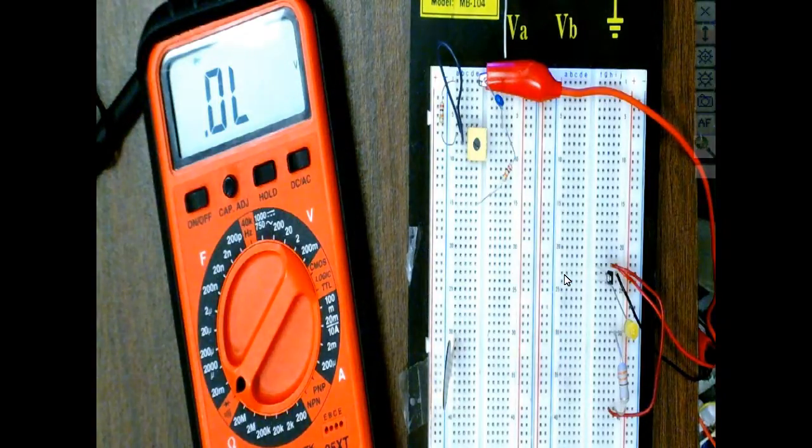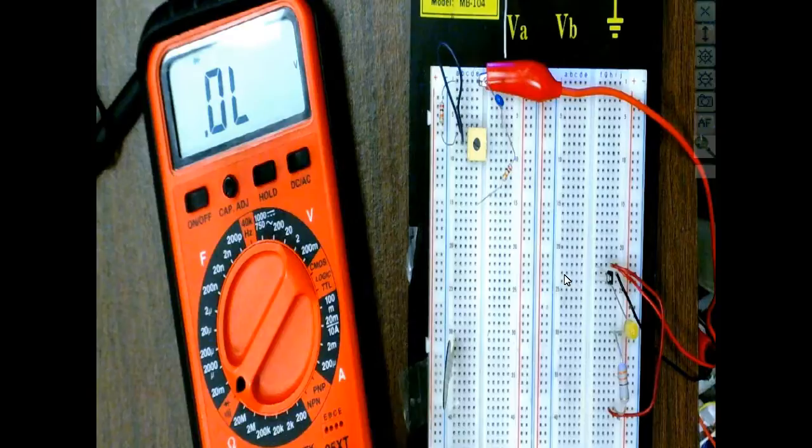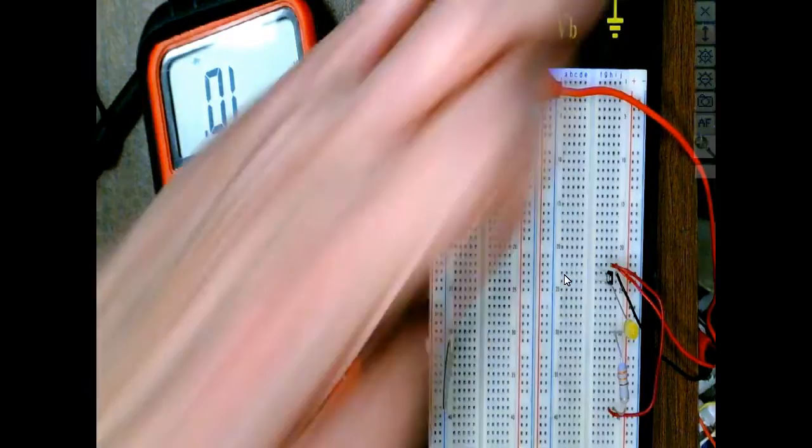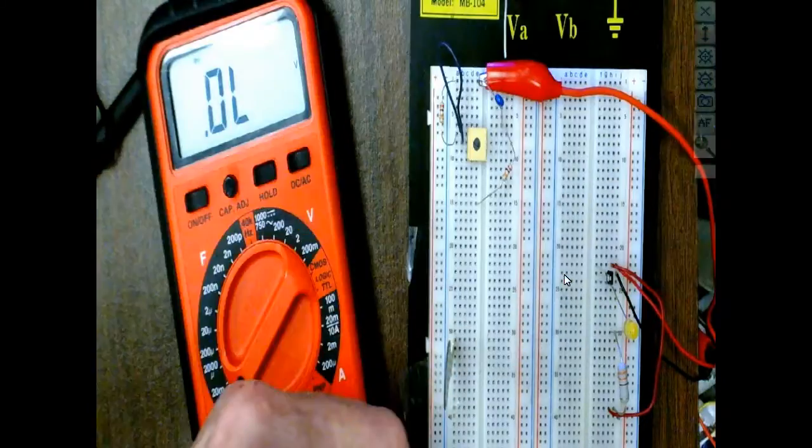Larry was telling me about a system they have at Mercedes where a cart's moving down and it goes past one magnet and the cart speeds up, and then it goes past another magnet and it slows down. That's basically nothing but a Hall effect sensor on the cart, and they have magnets out there. One uses a north and one uses a south, so the PLC that's running the cart knows when to speed it up and when to slow it down. Ain't that neat?